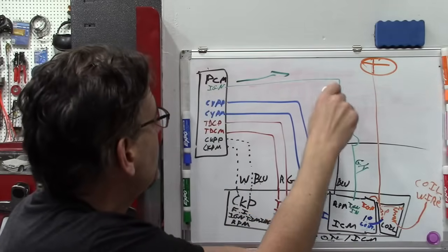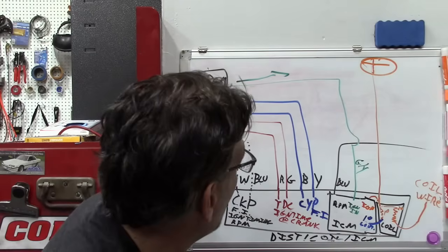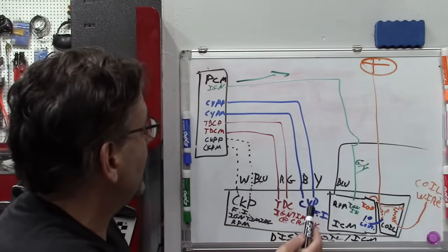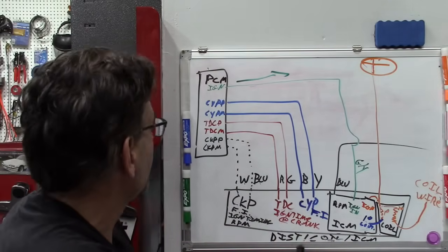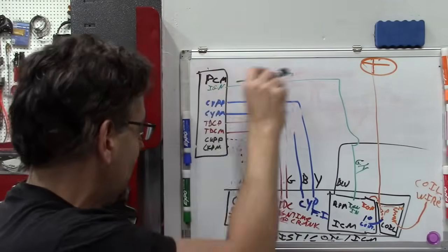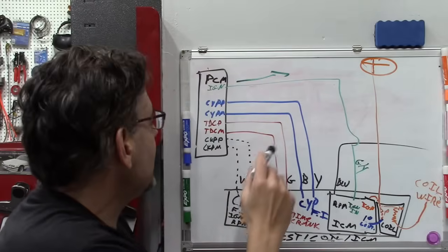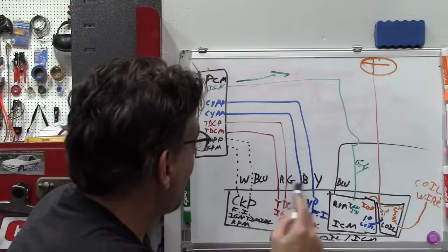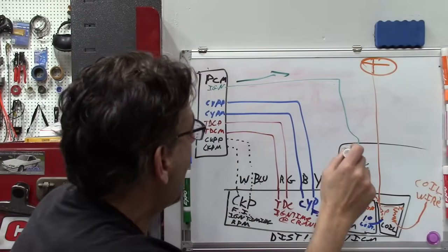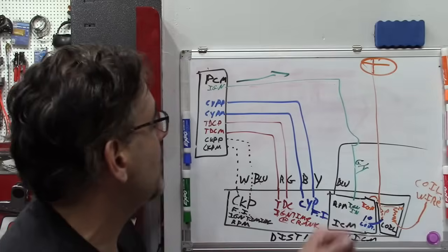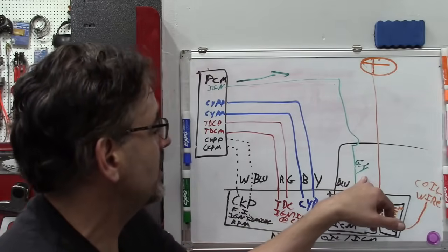Again, we tried to put my own ignition signal into the coil, but I am also convinced that these sensors ultimately produce that ignition output from the PCM. I think I can test all of these at once if I can crank the engine and verify there is a signal on this green-yellow wire.